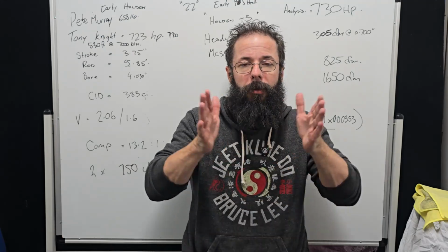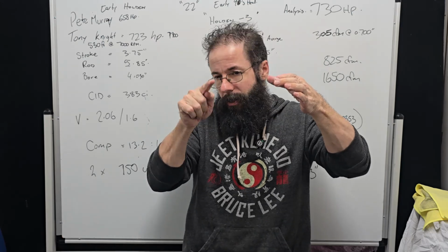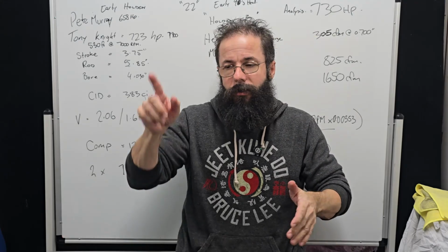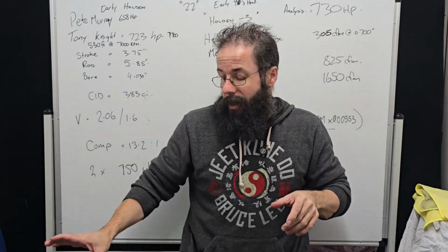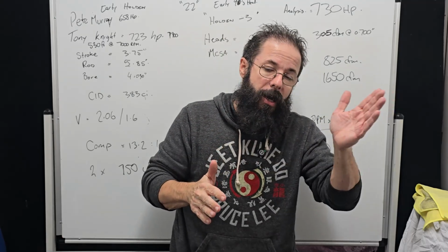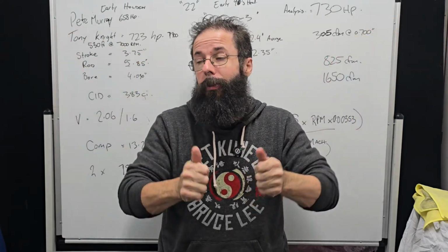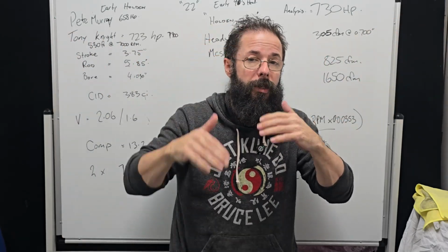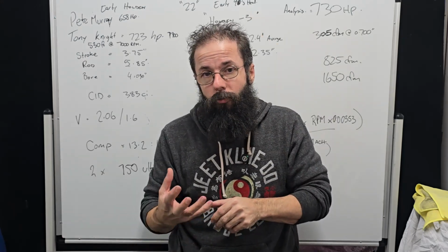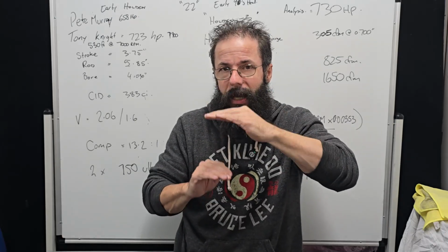But with a tunnel ram, because we have this extra area at the sides and we have the hole there, this whole area will be in a negative pressure because we get this stream coming in like that. So this is negative pressure here. So any waves that come into the plenum, again, back to our basics in our other video, a high pressure will go to a low pressure. So what actually happens is they get washed out, they get pulled out into the corners, and we get very little signal coming back into the carburetor, but we get a nice clean signal from the runner itself because the carburetor is much closer to the runner and there's a distance we play with there.